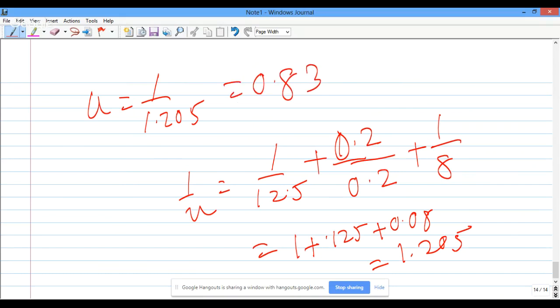Now, supposing my temperature difference between outside and inside, let me take a steady situation, which means in a periodic situation also, as we have said, our temperature varies in this manner, diurnal temperature, not exactly sinusoidal, but periodic. Whatever the temperature is at 8 a.m. today, tomorrow also it is likely to be similar, except for seasonal change. So the mean inside and mean outside nearly remain the same.